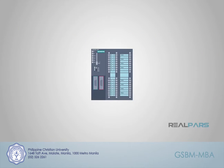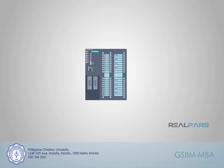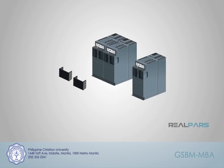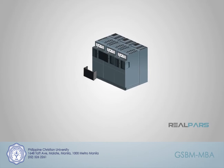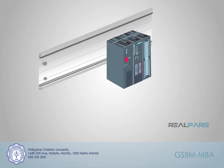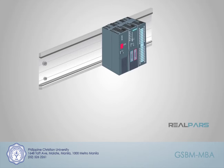An installed PLC is deceptively simple in appearance. You have a CPU module and input-output devices referred to as I/O. Sometimes the I/O is part of the CPU, and sometimes it is in other modules. The CPU communicates with the I/O, so in most systems, they share a backplane that physically holds them in place and electronically connects them.